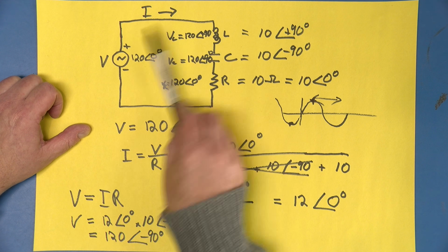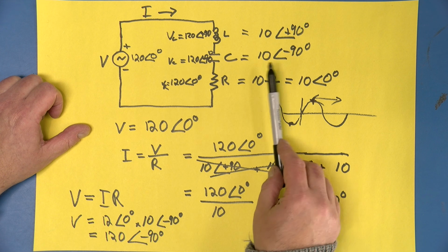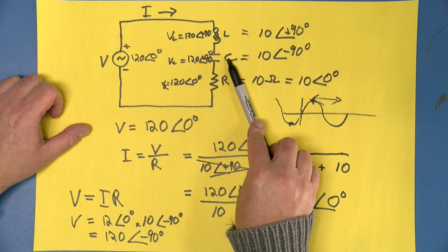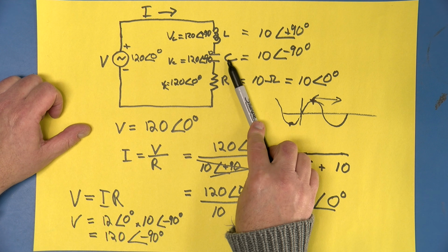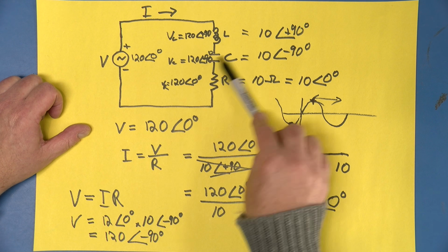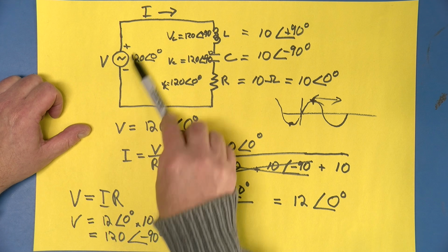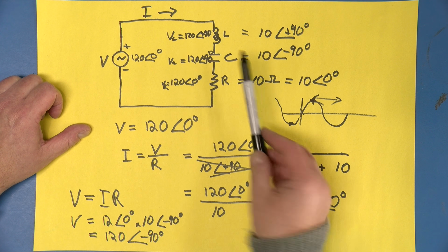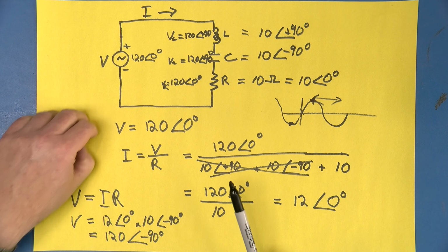And for the radio stations at all the other frequencies, well, suddenly the L plus C no longer cancel out, and so they start using up more and more of the voltage from the antenna, and the amplifier gets less and less. So that's a very simple tuned circuit.